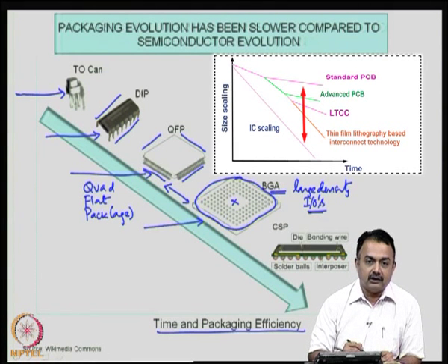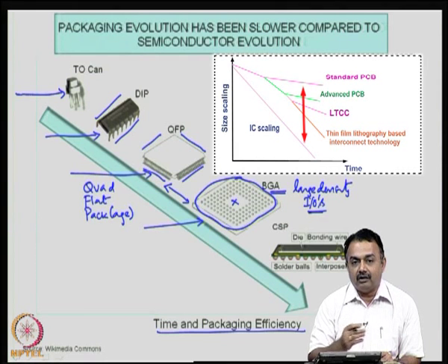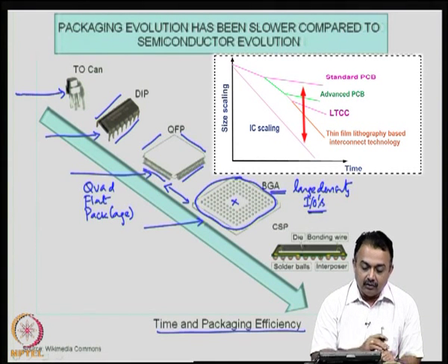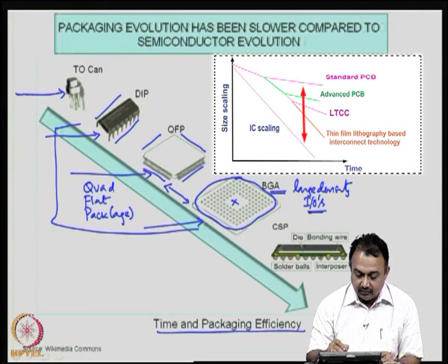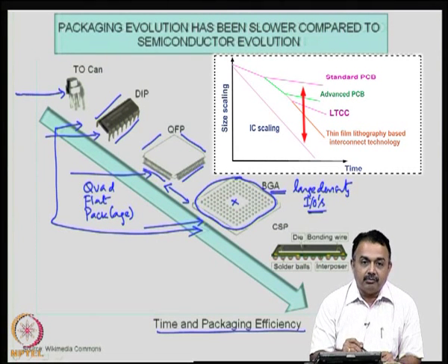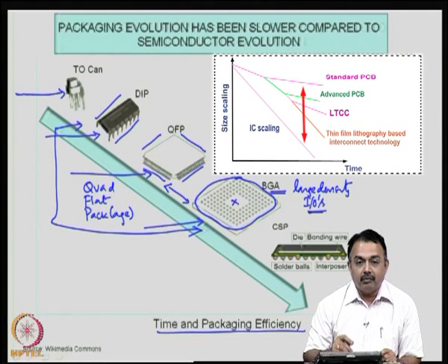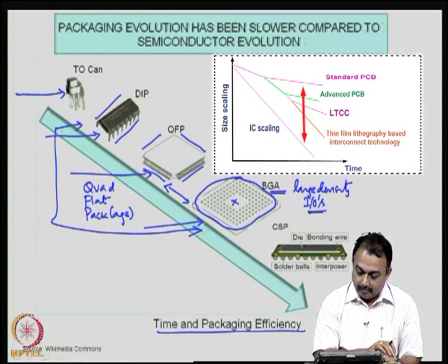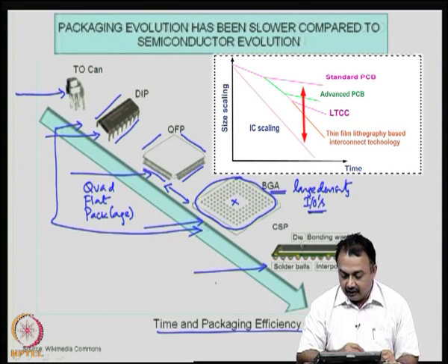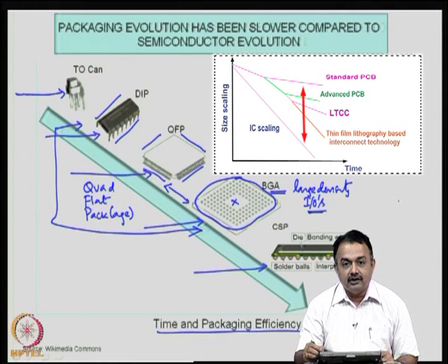So, as I mentioned in one of the slides earlier, BGA is the workhorse of the industry today. More and more designs are being converted into ball grid arrays, because you can look at it rightly from the dip package to the ball grid array. This is a very large package, dip package, whereas a ball grid array package is definitely smaller in size, and at the same time in terms of performance you can expect more reliable performance electrically and thermally. Then we are now again looking at new packages called chip size packages or chip scale packages.